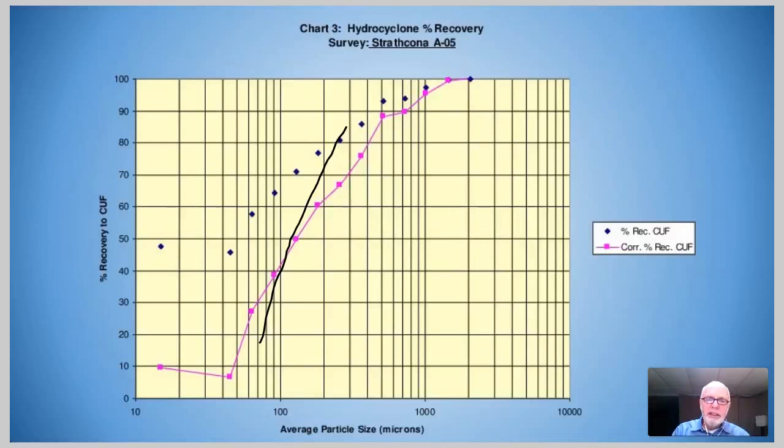But another advantage of the new modern cyclones is they have a lower pressure drop at the same flow rate. So with the same pump and cyclones, we can increase the flow rate through the cyclones. That is, we could increase the circulating load ratio, or we could improve the water balance. So we want to take advantage of that.